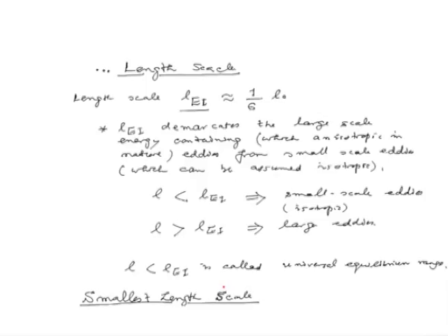For viscosity to become dominant, the Reynolds number linked to the eddies should be roughly of the order 1. So, that is what we are looking at at the smallest level. Now, Kolmogorov came up with the estimate of these length scales. That is why they are called Kolmogorov length scales, and they are defined in terms of the energy dissipation.